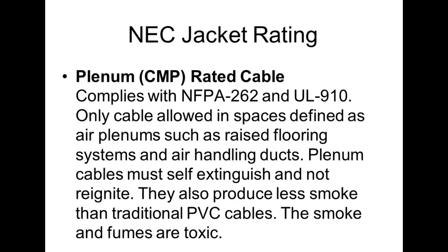The jacket rating: we have plenum rated cable, so if you see a CMP rating on the jacket, this is for plenum. So y'all know what the plenum is now. What's the plenum? Actually, it was the space between the ceiling and the suspended ceiling that was used for air conditioning. But over time, it became known as the space between a suspended ceiling and the actual true ceiling. So everything up in there would be considered to be plenum. We're not supposed to run regular cables up in the plenum.